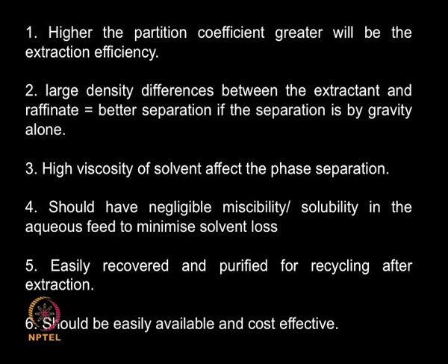With a large density difference between the extractant and the raffinate, you can achieve good separation using gravity alone. That means after the mixing you can allow them to settle from each other, and you will get a very nice phase separation because of gravity. But if the density difference is smaller, then you may have to resort to some sort of centrifugal separation.